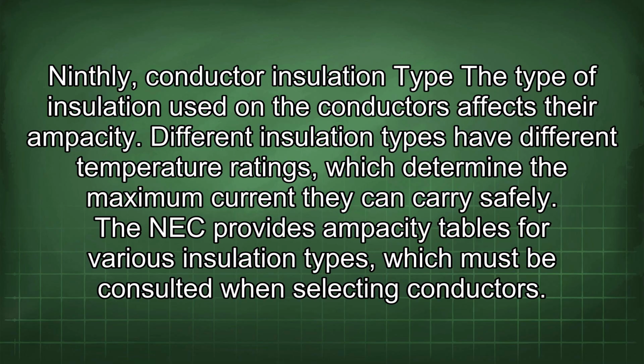Ninthly, conductor insulation type. The type of insulation used in the conductors affects their ampacity. Different insulation types have different temperature ratings, which determine the maximum current they can carry safely. The NEC provides ampacity tables for various insulation types, which must be consulted when selecting conductors.